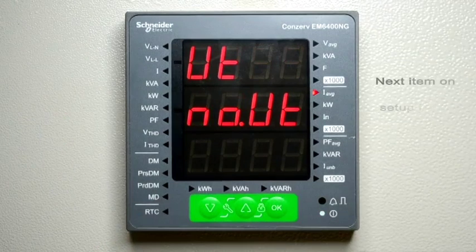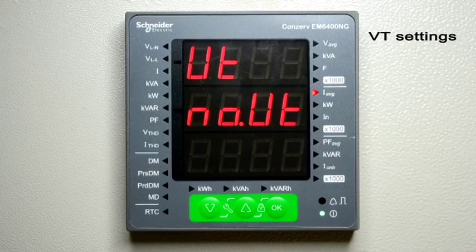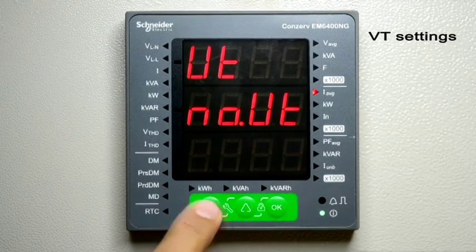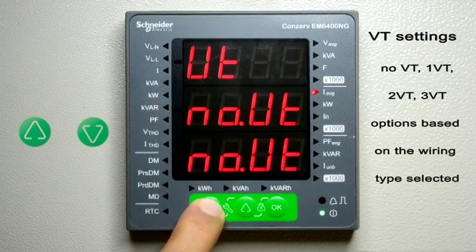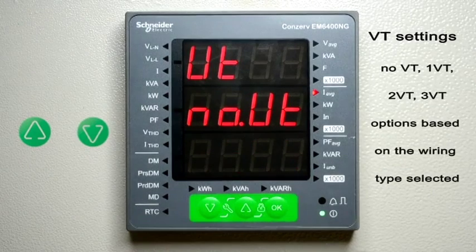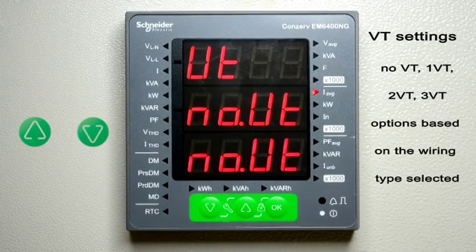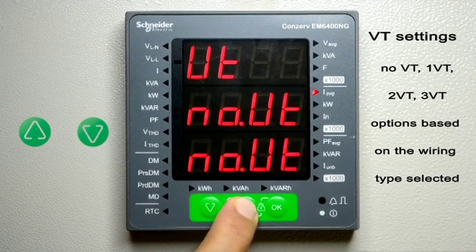Next item on setup is voltage transformer connection. This page is used to configure how the voltage inputs of the meter are connected to the system. To change the voltage transformer configuration, press OK and then scroll through the available VT options. If the meter is directly connected to the voltage lines of the system, choose No VT. If voltage transformers are used for connecting the voltage lines to the meter, choose appropriate number of VTs by scrolling